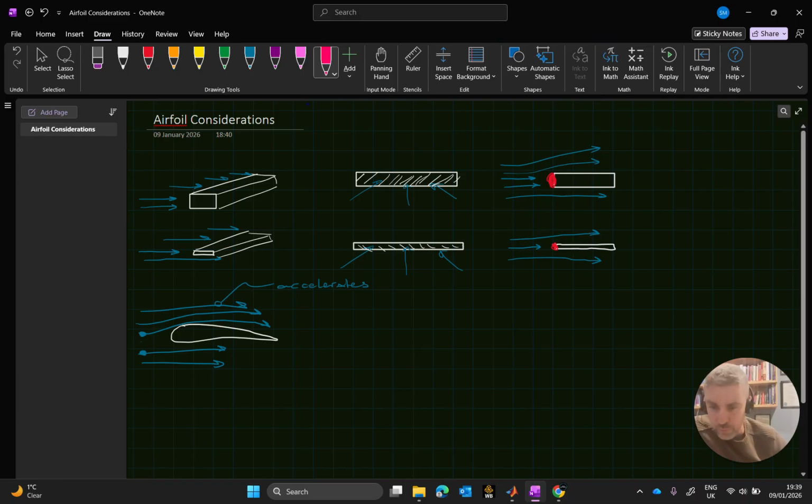Now, there's another thing in that as well. There are also schools of thought which talk about the air being pinched, because this bump here just drives the air up into what would otherwise be non-affected streamlines up here. Now, in fact, they are affected for multiple chord lengths up above it, but at some point they aren't.